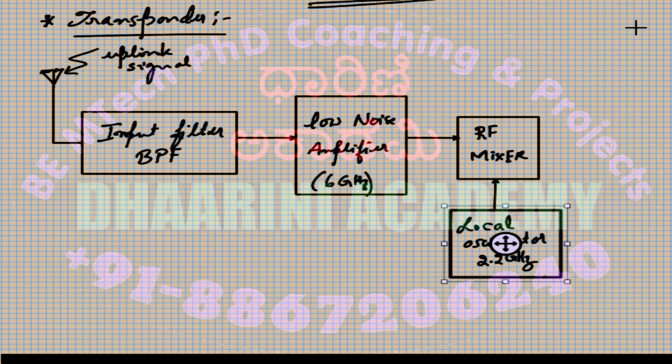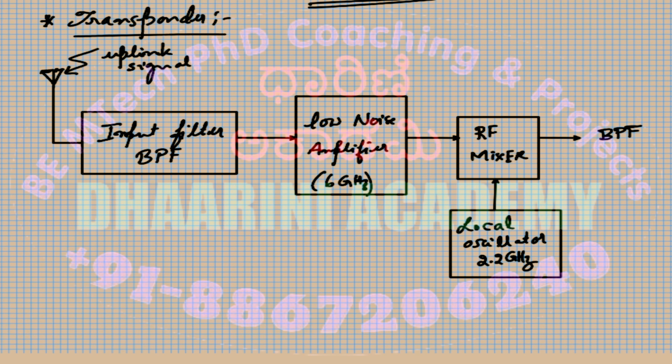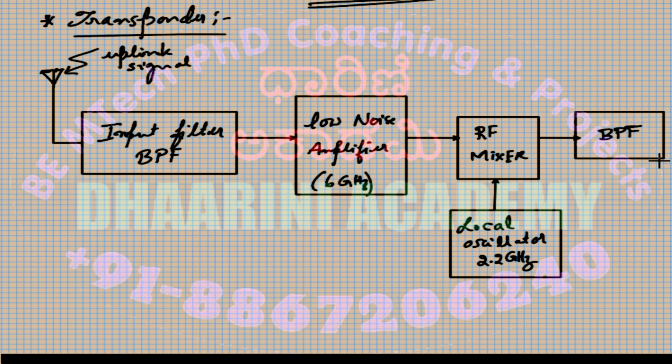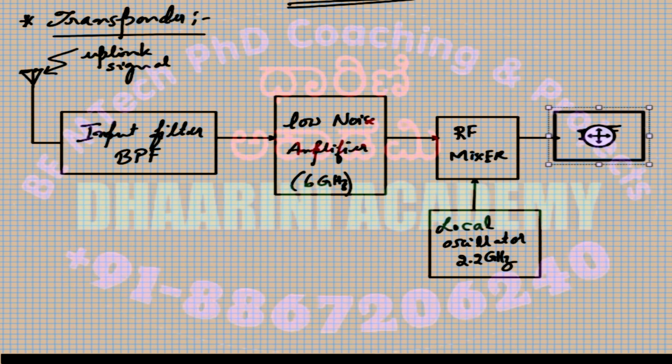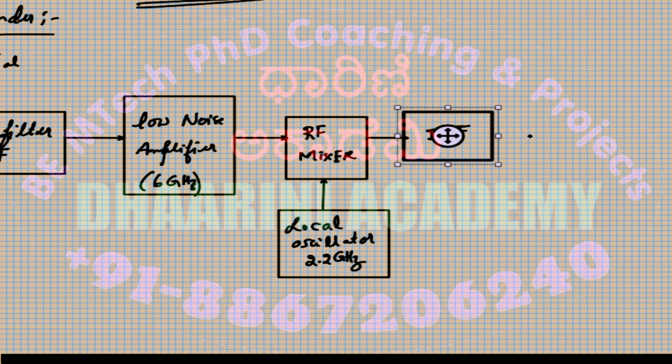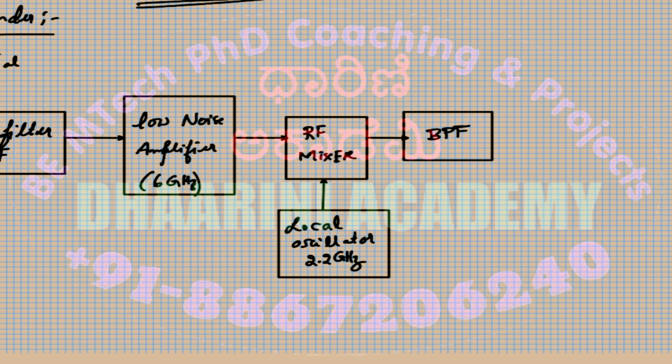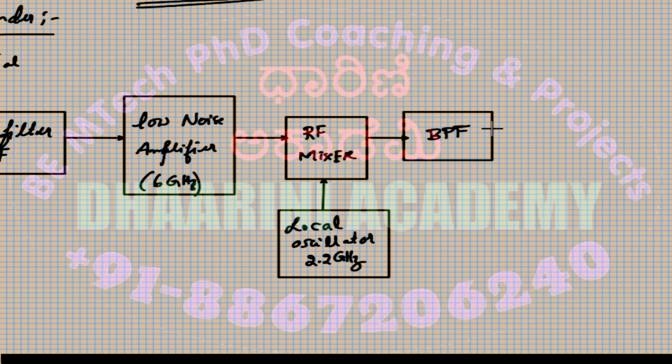So how to select that? Again, I use a band pass filter centered around the required band of frequencies. So it will select that frequency. Then I need to put it into an amplifier, only that. Around 3.7 to 4.3, whichever is the frequency that you are using, that will be amplified now. You tune this BPF to the central frequency of that band so that it will pass anything that comes in the downlink frequency.